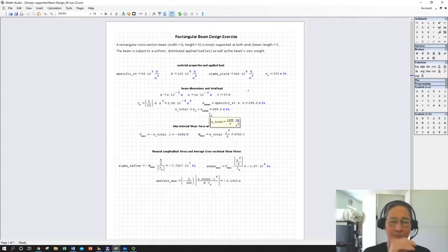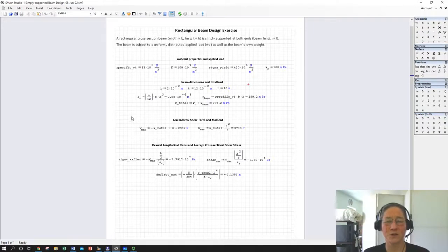But this is an example of why, depending on what your scenario is, it's very important to consider material weight. Metals, concrete, things like that will tend to have dead loads due to the material weight itself that could be significant compared to what you're trying to hold up. Things like composites, fiber reinforced materials, even wood might be less significant. But it's always good to check, especially if you're pushing a safety factor, which you should never do.